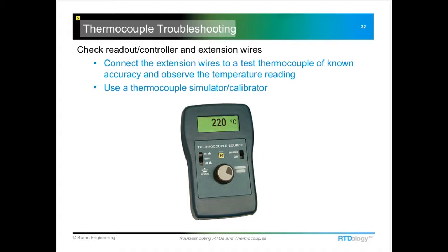And then the other, drift from calibration data over time. Yeah, both RTDs and thermocouples will drift, and it depends on the way they're used. Again, high temperatures, temperature cycling, vibration, shock, all those things are going to cause both technologies to drift over time. Thermocouples can get contaminated from the process when used at high temperatures, and that's going to cause them to drift even faster.